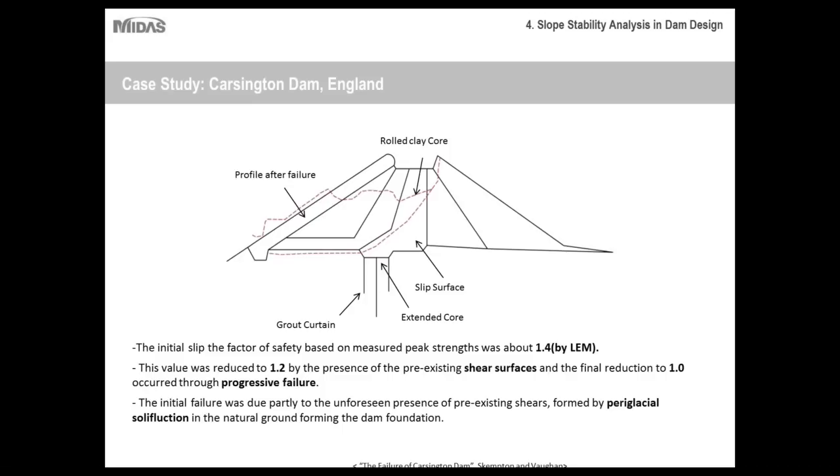As you can imagine, when water freezes, it expands. So just imagine all of the water in this dam expanding over the course of a winter. That'll cause some breakage or some shear forces within the dam. And then imagine all of that water melting during the spring and maybe seeping out. Those shear forces are going to be increased. Imagine this happening periodically over a couple of years or even a couple of months. That's eventually going to cause so much shear within the dam that it failed.